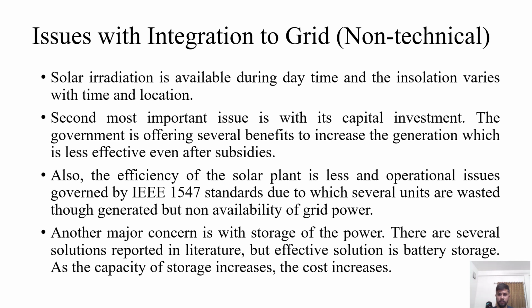So first of all, before moving to the technical constraints, we are dealing with the non-technical issues with the integration of these renewables into the grid. Solar irradiation is available during daytime, and the insolation varies with time and location, hourly and from place to place. This is the biggest challenge with the integration of renewable energy resources, especially solar.